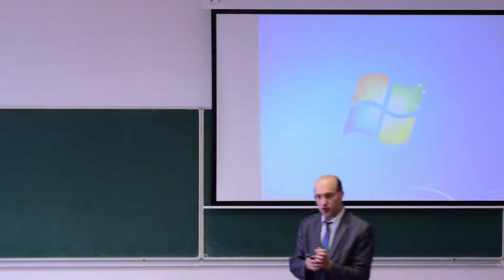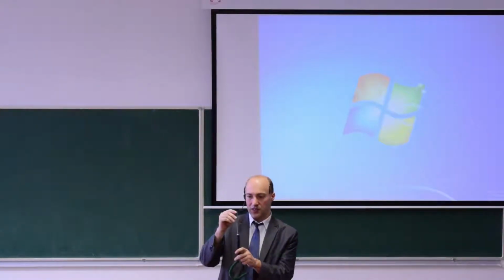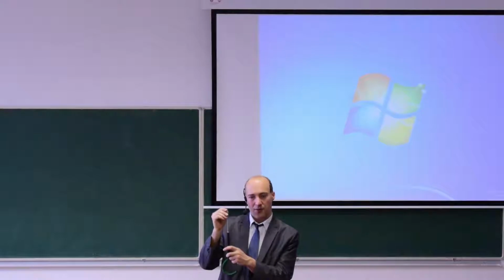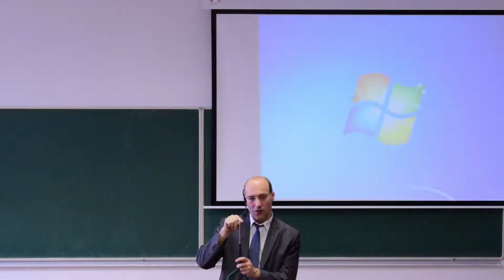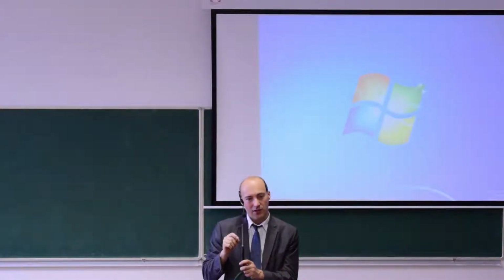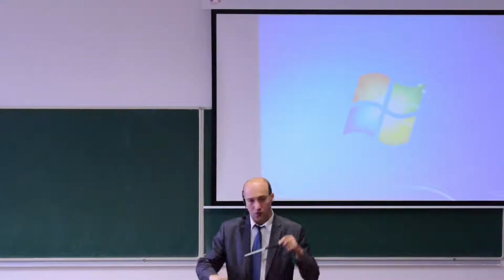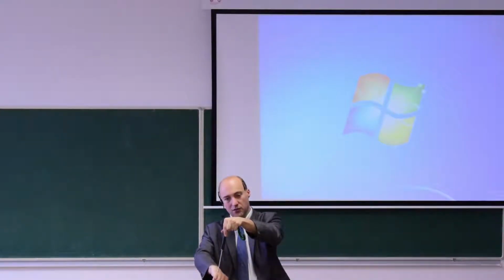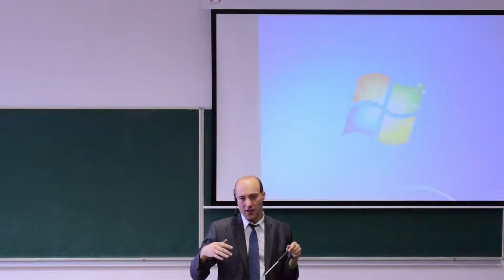It's a little bit larger. So here it's a contact thermometer. On this tip we have a thermocouple, and it is welded on a copper ring so that it has good heat conductivity. So for example, if I want to measure temperature somewhere, I place the contact probe and I read what is the temperature of the object.